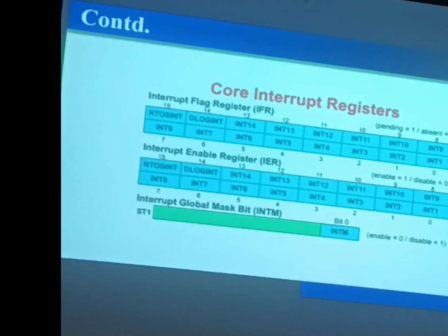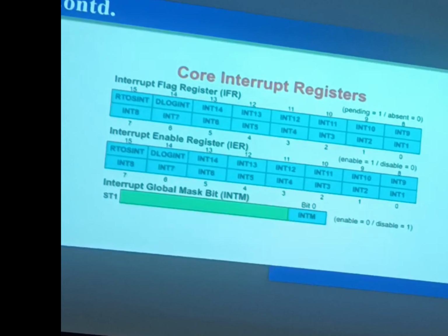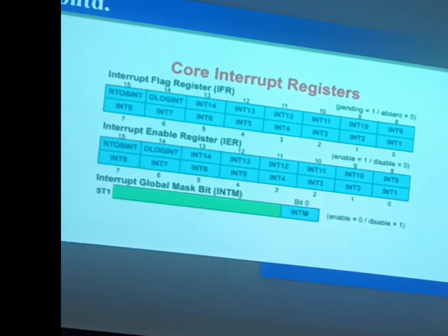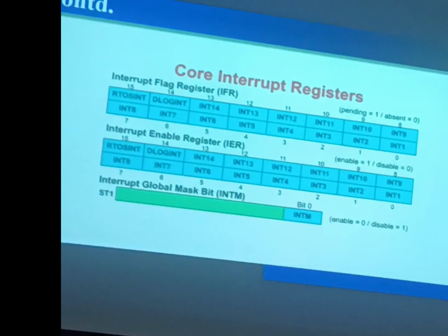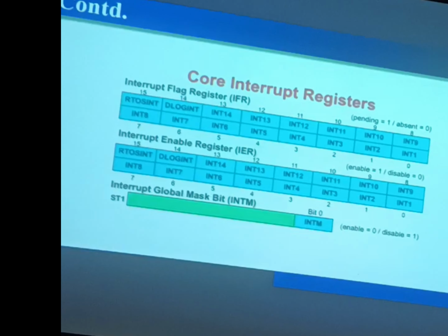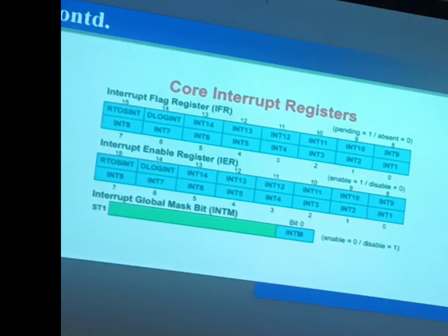Okay. There are three major registers: the interrupt flag register, the interrupt enable register, and the global interrupt register. The global interrupt register is INTM. If that is on, then only you can start all the interrupts.